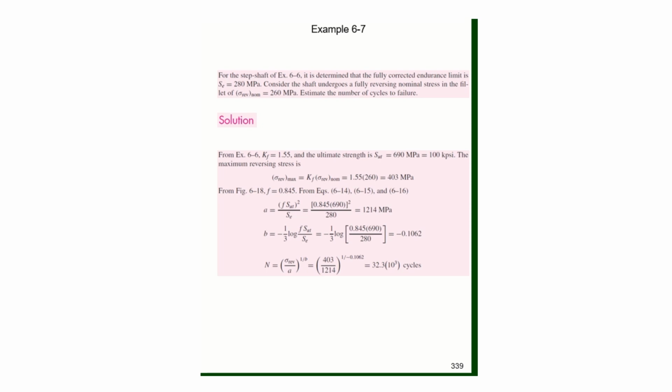In this video lecture, we are going to continue our discussion of fatigue, and we will work several example problems. We will then get into fatigue based on non-reversed loading. To begin with, these examples are based on what we call completely reversed loading, where the load goes from a tension magnitude to the same magnitude in compression, and we would oscillate around a force or a stress of 0.